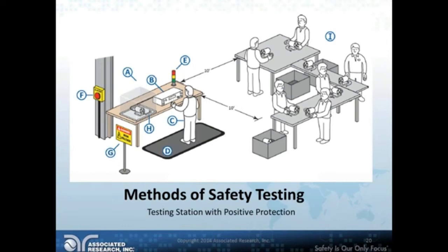And then, of course, there's an e-stop switch in that entire station. E-stop switches are usually wired up to station power, not just the high pot tester, the whole station. So if there's a problem, somebody's getting shocked, somebody can walk by, slap that e-stop, and it cuts off power to the entire testing station.